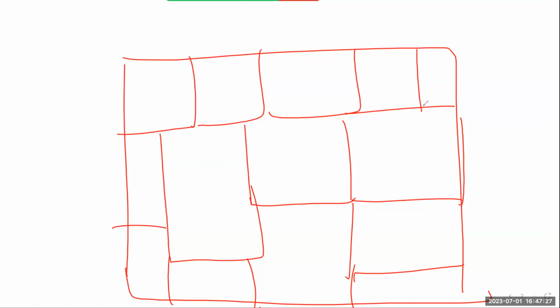So in this particular way, what is happening? You are utilizing your wafer 100%. Because the way you have calculated the wafer area, you have calculated it from the standard cell point of view. In a standard cell, after the logic synthesis, whatever the standard cell count was, you say, okay, in this particular design these many AND gates, these many NAND gates, adders, multiplexers we have used. And on the basis of that, you have calculated the area of your wafer. This is 100% utilized.